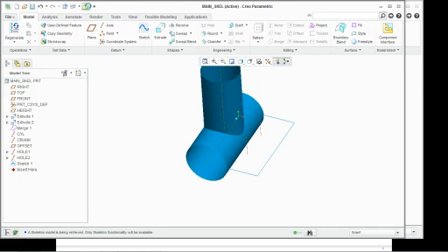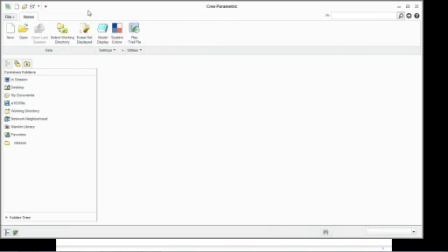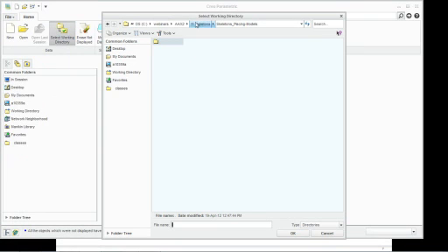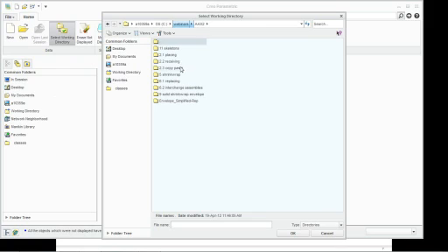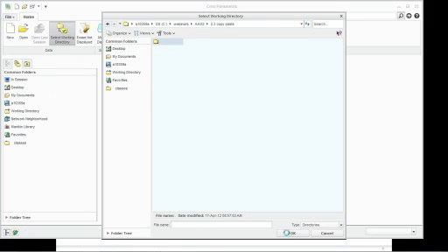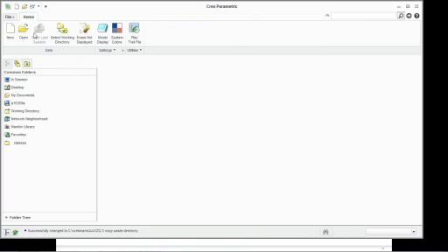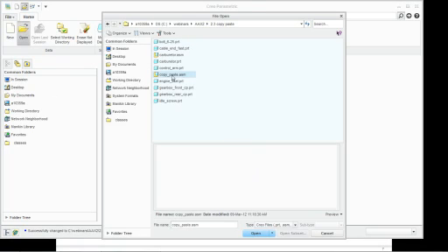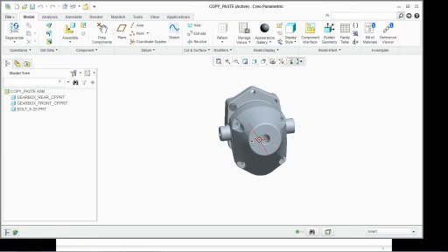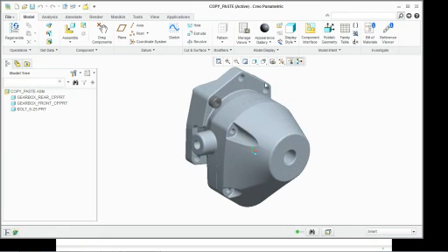If we go over to one of the more fun functionalities of the advanced assembly, copying and pasting. So let's erase not displayed, set the working directory to copy and paste, and we'll open up this copy paste assembly.